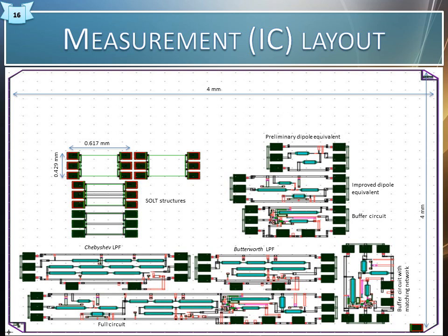Important considerations in such designs, as a result of high cost and long lead times, are placing each measurable item on the final layout to ensure that measured results can be obtained even if the circuit in its entirety does not operate within specifications. Since passive components are used in the majority of the designs as initially proposed, the circuit could be wafer probed, eliminating the use of external bond wires, which add parasitic components that need to be accurately modeled, and only requiring external connections to low frequency or DC connections.